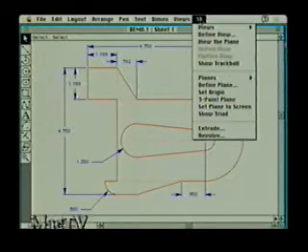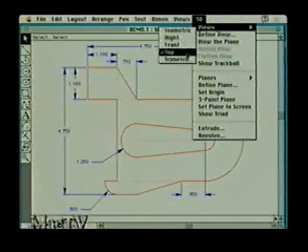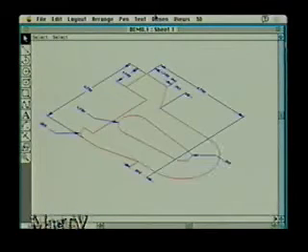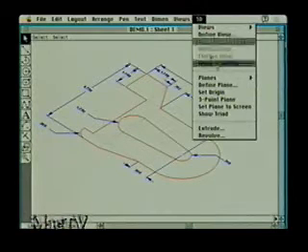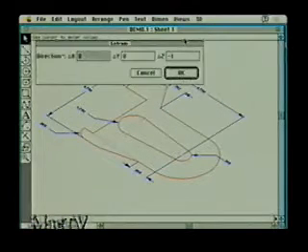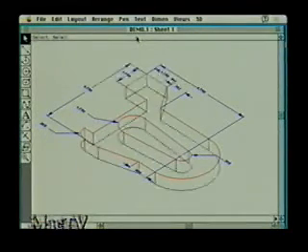Now, I can change my view here from a top view to like an isometric view. So look at that. It slants it off to the side. And then I can extrude this. Now I can take all those black lines and I can extrude them by pulling down, and it'll fill in a value for me along the z-axis, and I can say OK, and I get depth to all those lines.